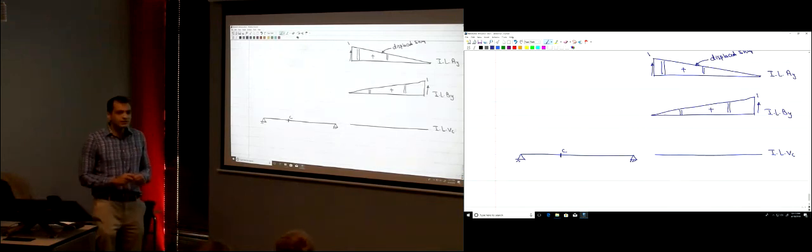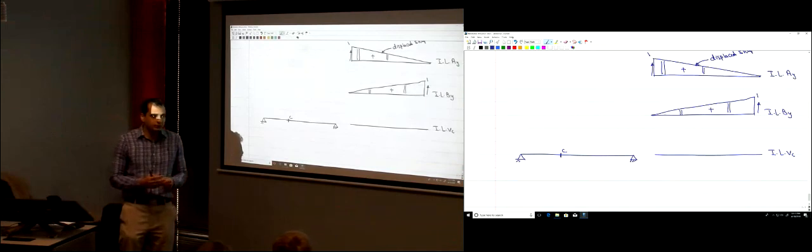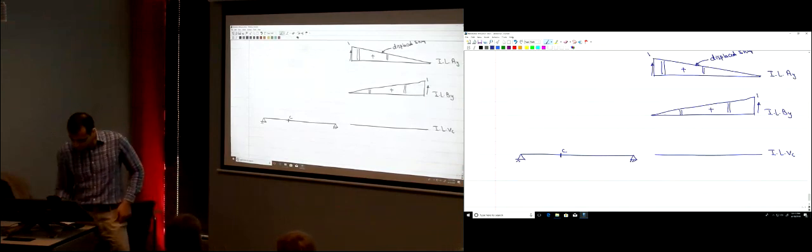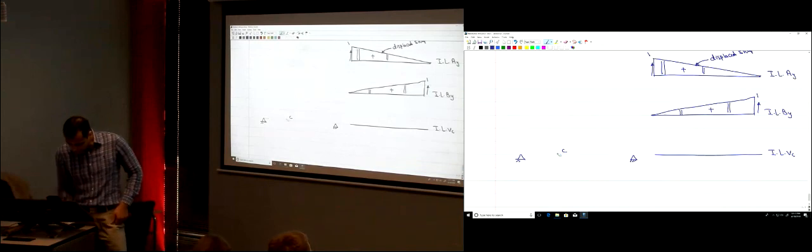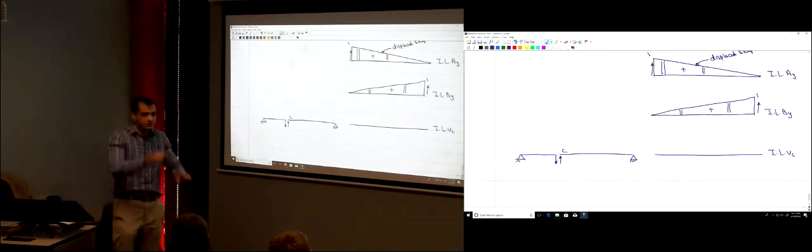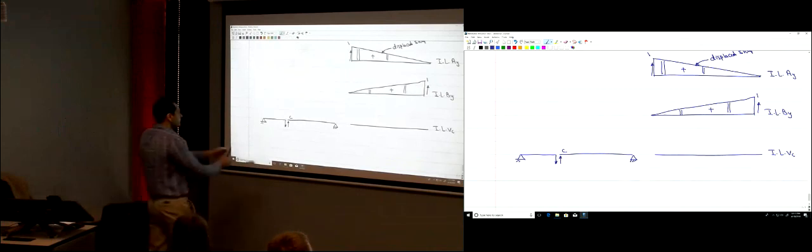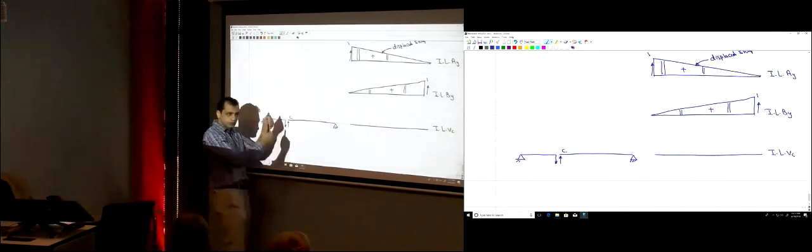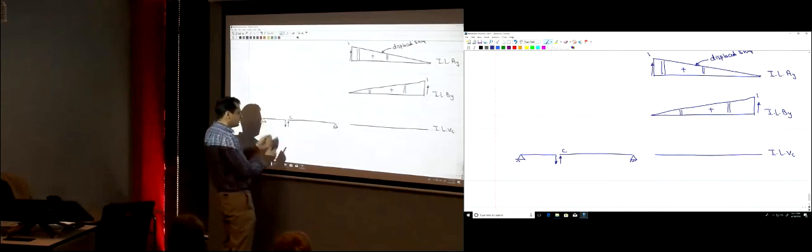The shear. What does the shear look like at the point? You remember the shear? How to get the shear? You just need to break the beam at that point, and the shear looks like two loads like this, right? That's the shear. So I'm just going to break the beam here to be able to put the unit displacement.